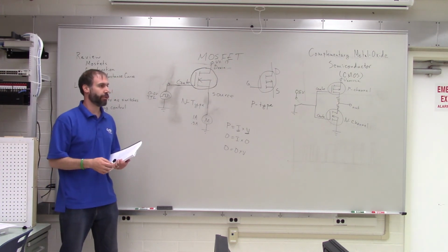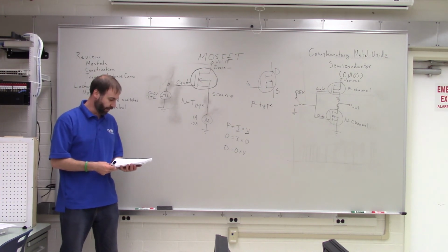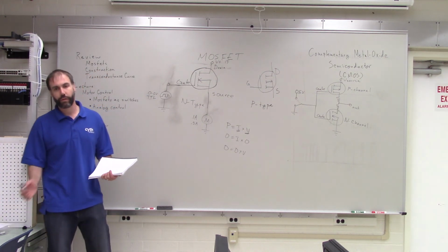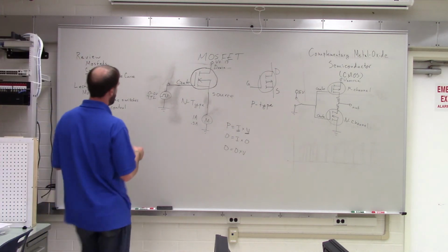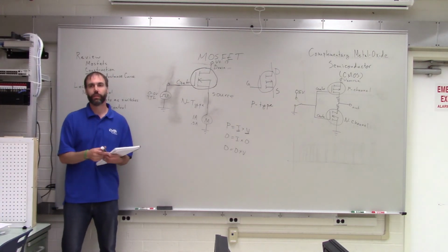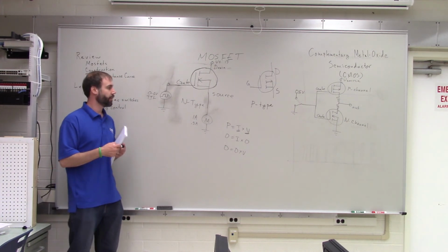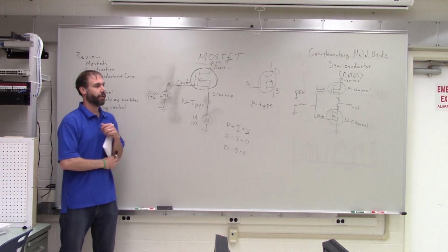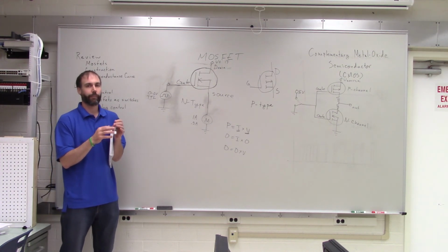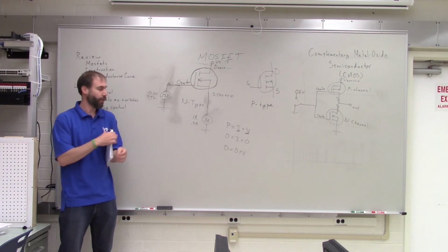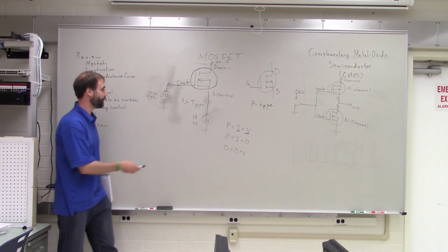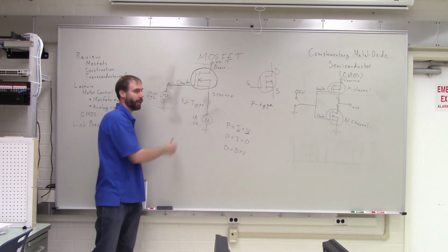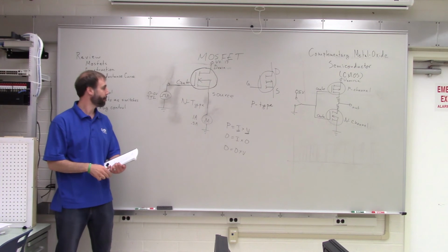And then what you're going to do is find the knob on your function generator that says duty, and you're going to pull that out. That will allow you to vary the duty cycle of the TTL. So remember we talked about how you could have a short duty cycle or a long duty cycle, a low or high duty cycle. So you pull that knob out and then you can change it around. And that should allow you to make the motor speed up or slow down. Okay?